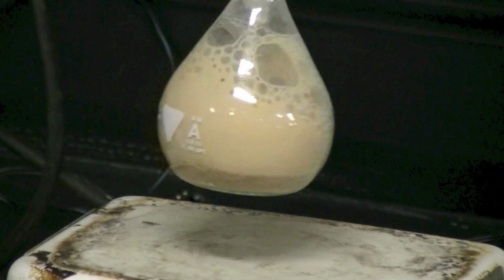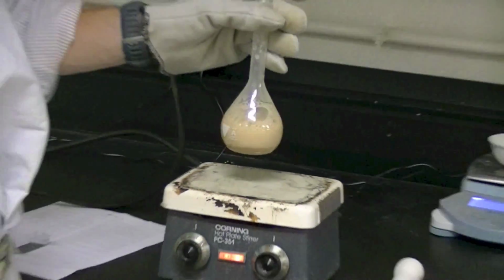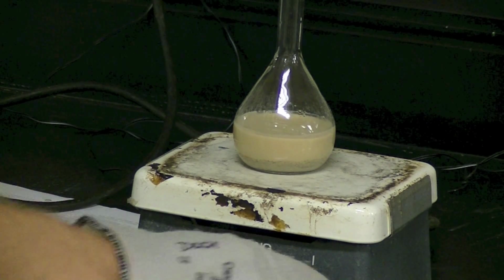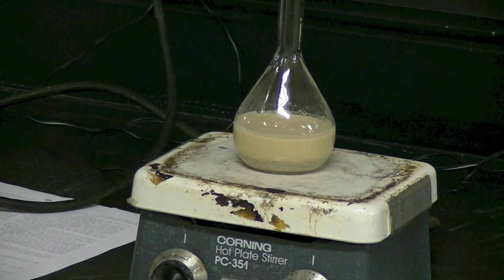Allow the slurry to just achieve its boiling point for a duration of 2 hours. Continually agitate during the 2-hour duration. Essentially, all the voids are being removed from the soil slurry at this time.